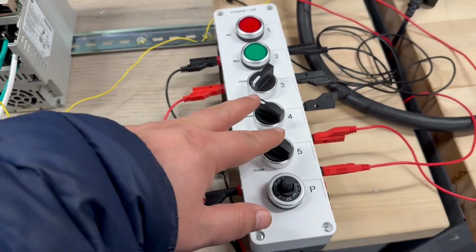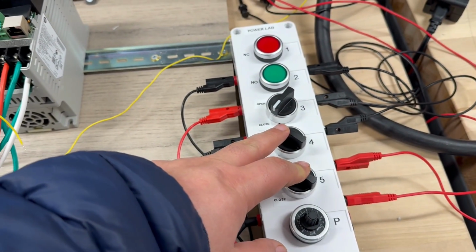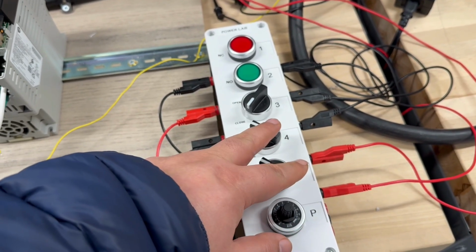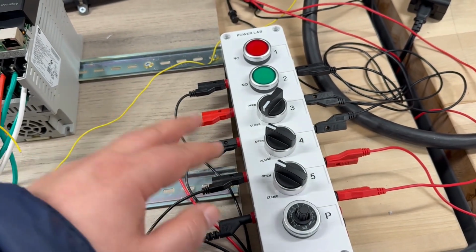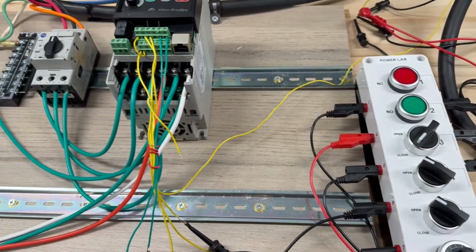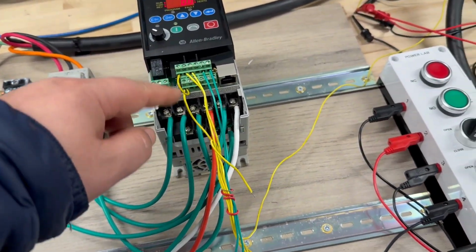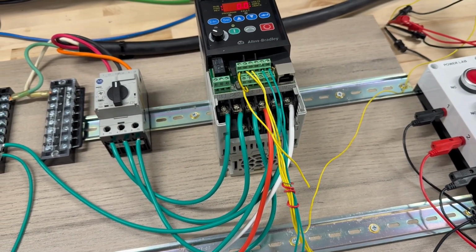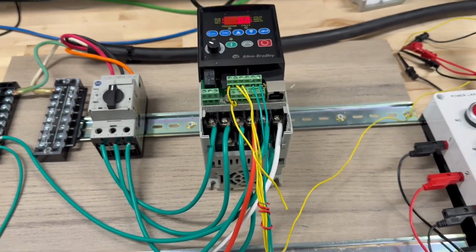Again, I added two more digital inputs, 5 and 6. One side of the switches is 24 volts, coming from port 11, terminal 11. The other side goes to ports 5 and 6. And I also brought back the jumper wire that we have between 1, 2, and 11.